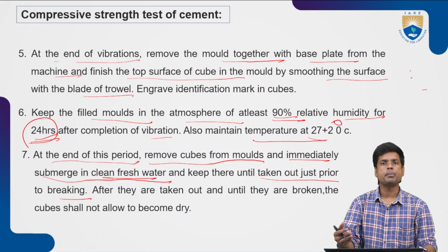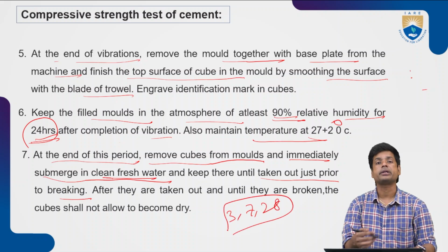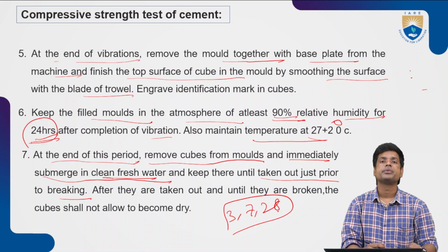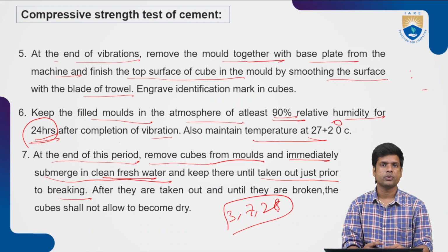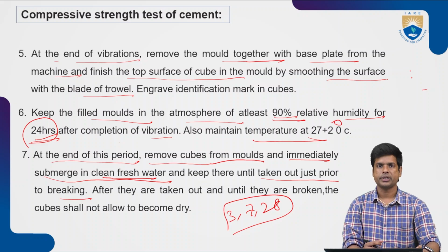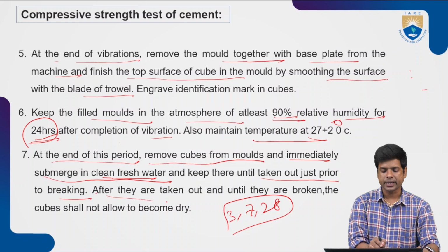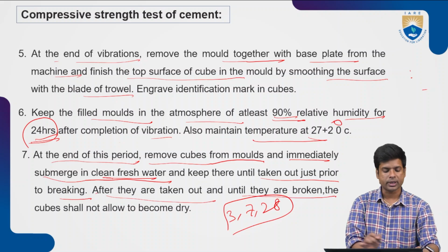Depending upon your requirement, like 3 days, 7 days, 14 days or 28 days, we cure it for different curing periods. Before testing only, take the cube out of the curing tank. After they are taken out until they are broken, the cubes shall not be allowed to become dry.